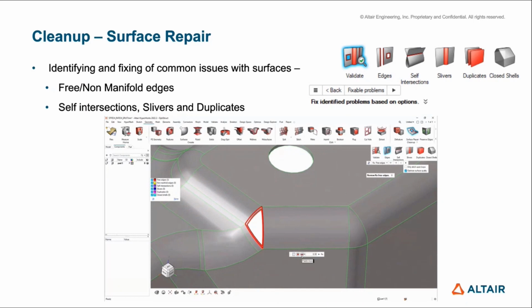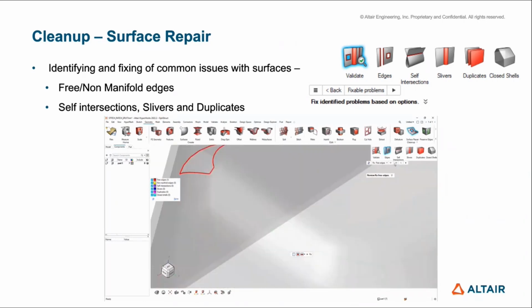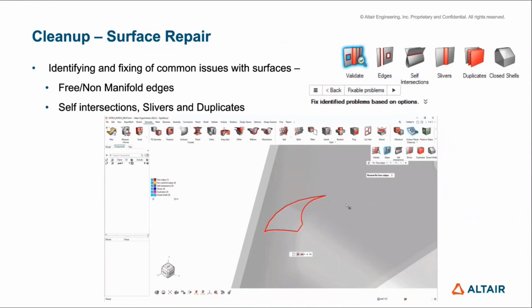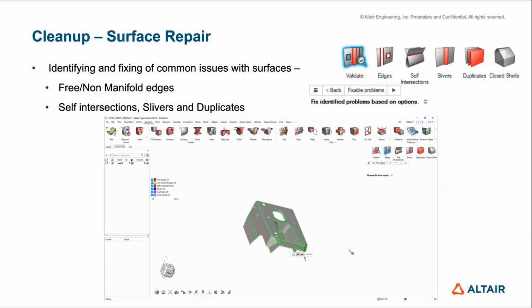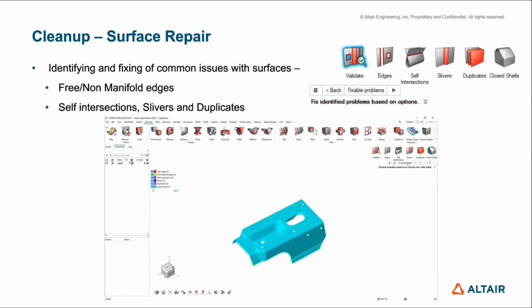each tool with the model tool options provided here. So there are delete surfaces, patch surfaces, stitch and stitch intersect, which are again more common. You can go through your model and fix these areas and get a closed shell, which is basically right before creation of the solids. Once they are ready, you can create a solid out of it and complete the workflow. You can click on legend to go to each of the errors.